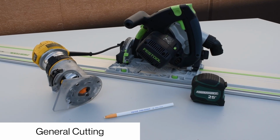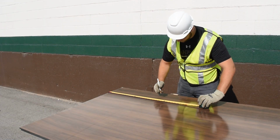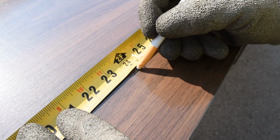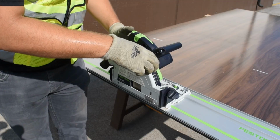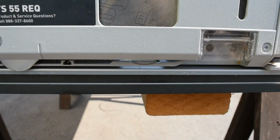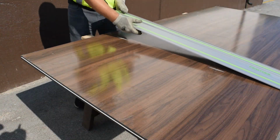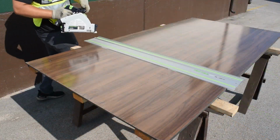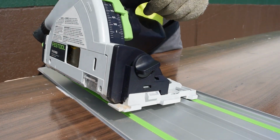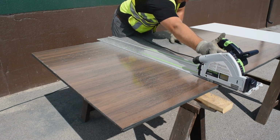The first process that we will be covering is general cutting. Make measurements and mark the panel accordingly. Always remember to measure twice and cut once. Set the depth of the saw blade to extend slightly into the sacrificial panel. Align the track of the saw with the measured mark on the panel. Snap the saw onto the track. Turn on the saw and proceed to make your cut.